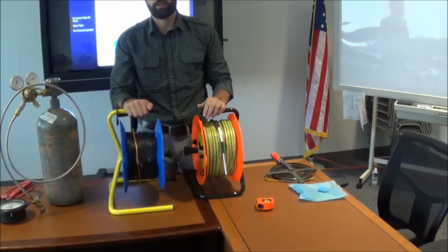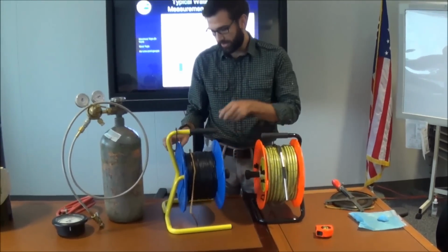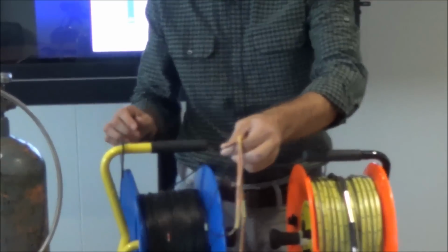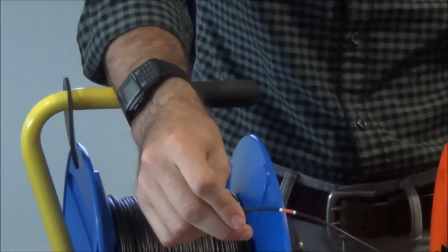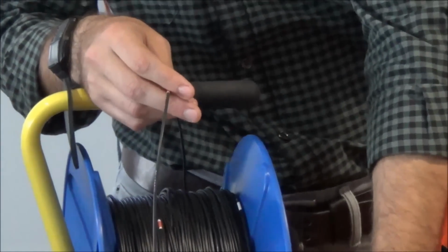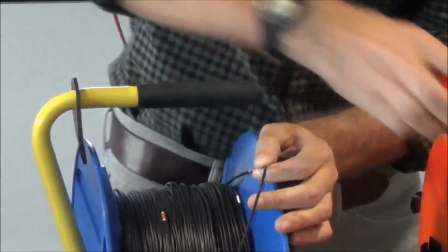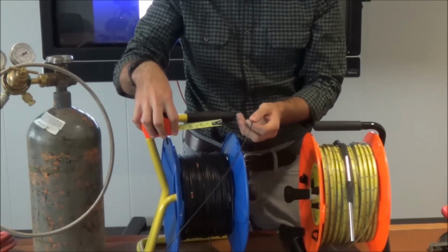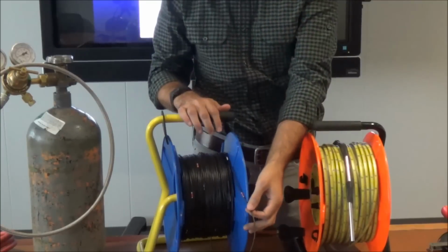Next is another variation of the electric water level tape. It's a coaxial cable. Same principle, also has 2 leads. But in this case, it's not calibrated. It's a kind of a thin line here. It's got markings at 5-foot intervals. So here's the first mark at 5 feet. What you would do with this is stick it down the well, get your measurement, pull it up, and then we use just a standard tape measure here. This one is actually in hundredths of a foot, and we just measure down between those 5-foot intervals to see what our water level is.